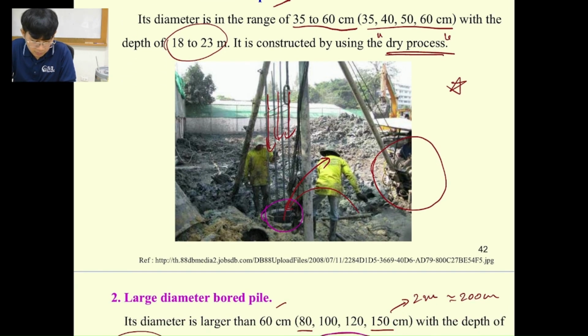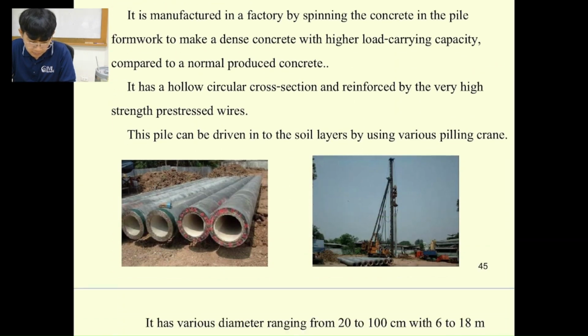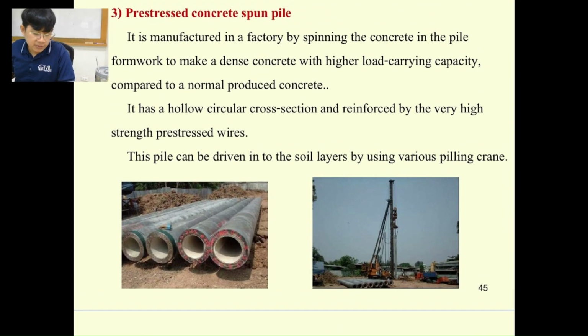They need to use the bored pile only. Okay. And next one is going to be the pre-stressed concrete spun pile. This one is a hybrid between the bored pile and the driven pile, because this one has a really high density,